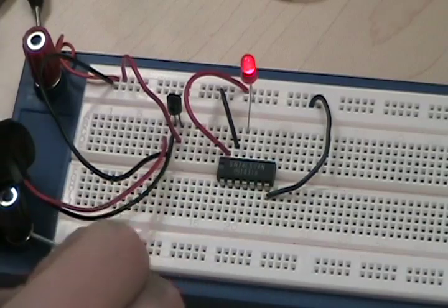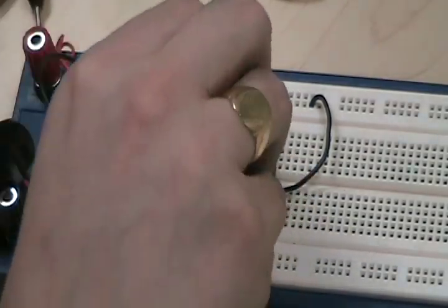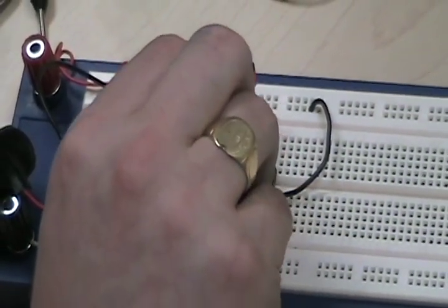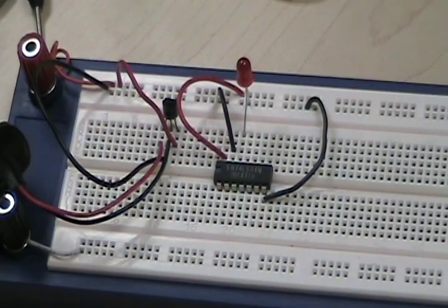As soon as I unplug this, by default the input is going to assume 1, which is going to make the output go low. So right now the input is at 5 volts, the output is at 0 volts. It won't read 0 volts, but it'll be below half a volt. Usually inputs of digital devices, especially TTL, read 0.8 volts and below as low, and above half VCC, which is 5 volts, above 2.5 to 2.8 volts is considered high.